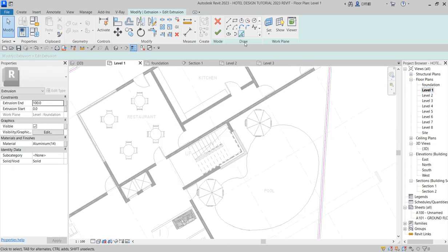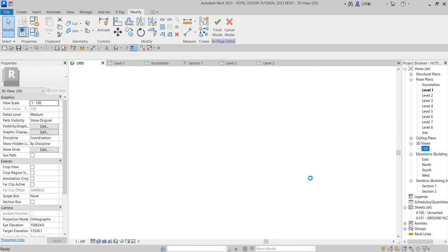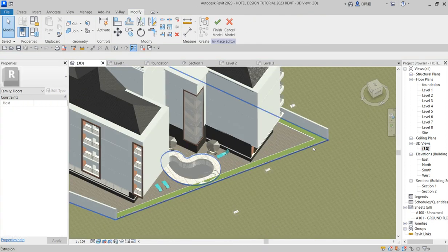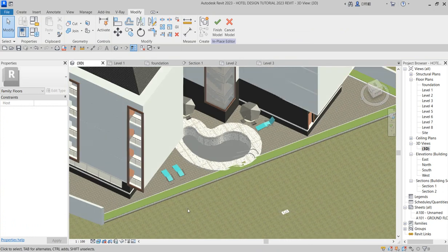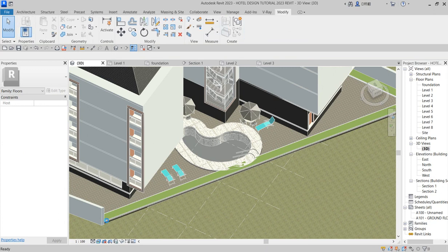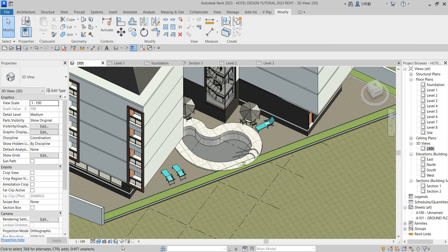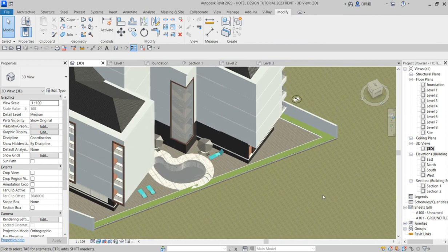So for that swimming pool part, you create the space, quick finish. So when you look at it in 3D, I think the problem is solved. Good. So these are the things you are able to do. You click finish and show your hidden wall by clicking here.